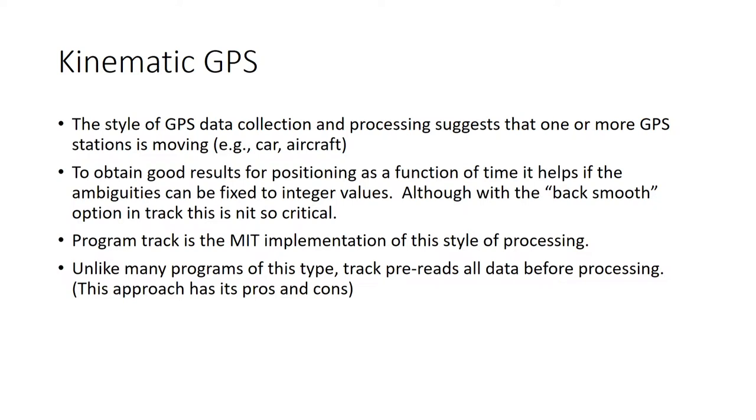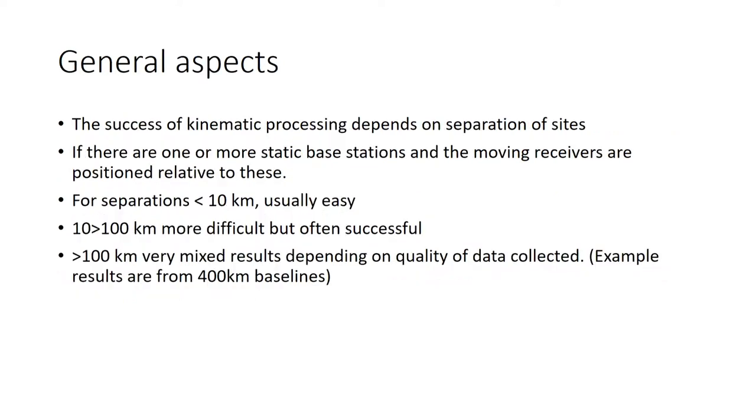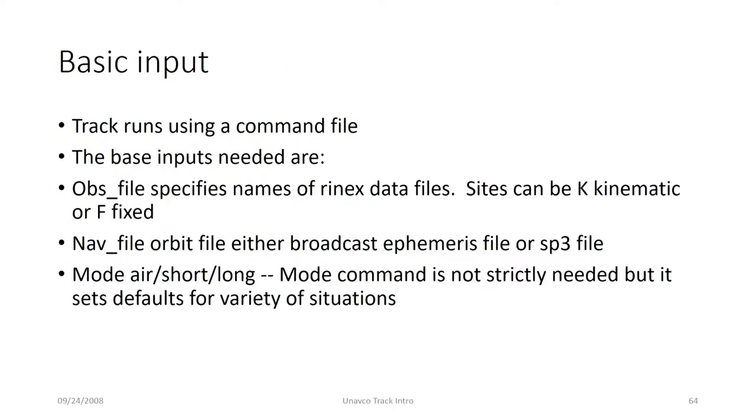And if it is moving slowly, then 15 second or 30 second is okay. But when you are looking for this co-seismic earthquake variation, then you have to have a 1 second sampling interval only. So these are some information about this track module.